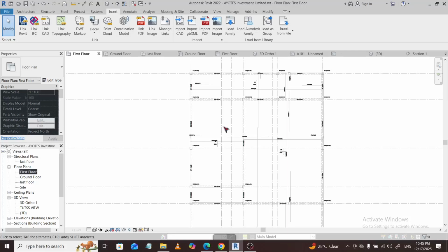In today's video, I'm going to teach you how to properly scale an imported DWG in Revit using type properties. If you've brought a CAD drawing into your Revit project and it looks far too big, far too small, or just doesn't match your building scale, the fix is straightforward. Revit lets you correct the scale by telling it what units the original DWG was drawn in. Once Revit knows that, it handles the scale factor automatically, so you don't need to do any manual math or